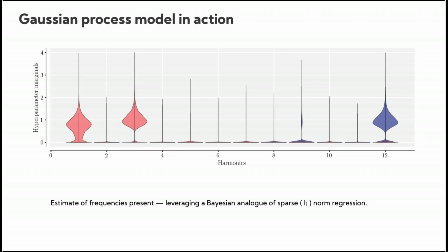At the back end of the compressor, you're looking at anywhere from 600 to 900 Kelvin. Back of the fan, you typically have close to ambient temperature values. So the sigmas are different, and that becomes a lot more important, as I alluded to, when you have a multi-plane model, where you take measurements from multiple planes and fuse them all together in a single Gaussian process model.